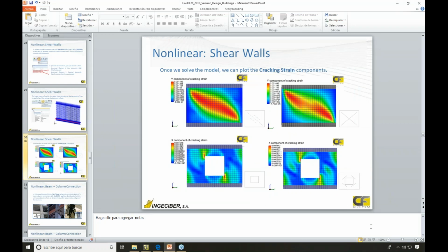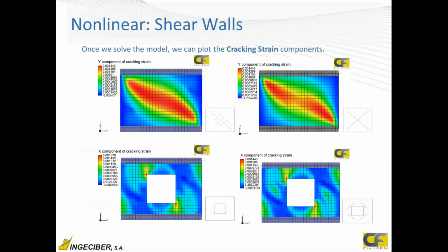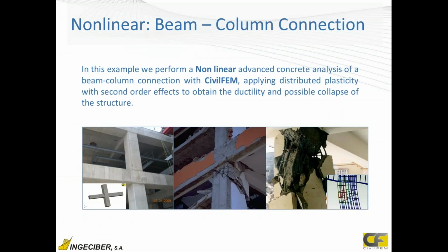Okay, so the next, yes, I want to explain everything, but I don't want to jeopardize your patience, so I will move to the next study in detail, which will be the connection of beam and columns. In this case, we want to reproduce a pushover in order to get our demand and capacity curves and retrofit, or even perform a cycling loading, with a nonlinear loading and unloading of this cycling load.